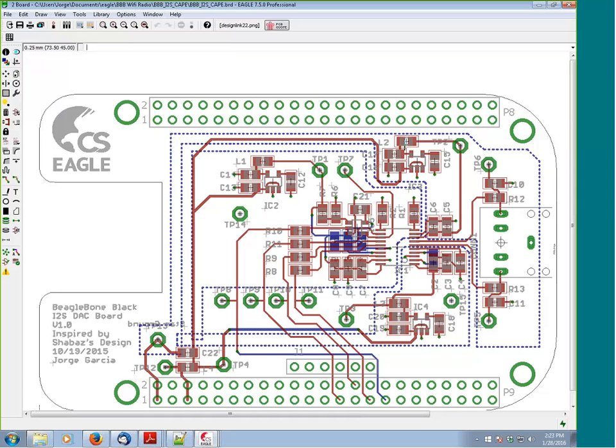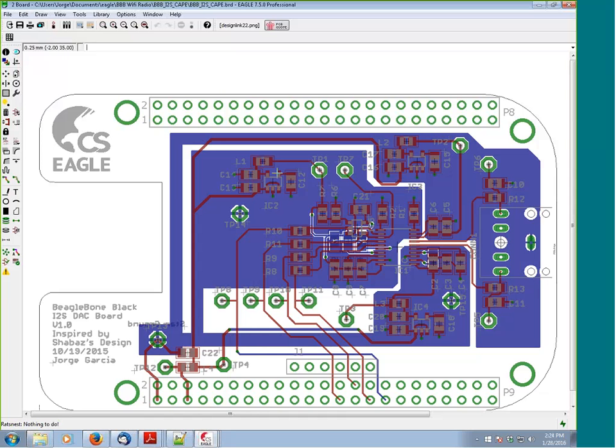As far as the ground plane, remember how I mentioned to you that the digital ground, the charge pump ground, and the analog ground all need to be tied together. I chose not to do that in the schematic, but rather here on the board. The way I did that is, as you're going to see now when I rat's nest, you'll be able to see the 3 different polygons. So what I did was I made sure they all return back to a common point.